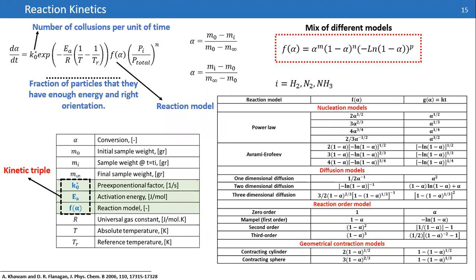Okay, we talked about the COMSOL simulation, but what about kinetics? When you talk about reactor design, what is the most important thing? It's kinetics. We know heat transfer, momentum balance, and mass transfer, so what is the rate of reaction? The most important thing for a successful simulation, regardless of your reactor, is applying the right kinetic model.